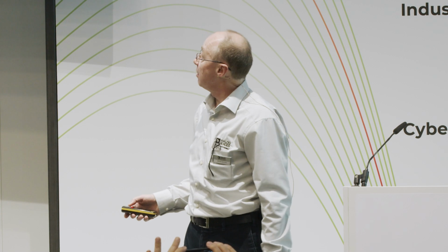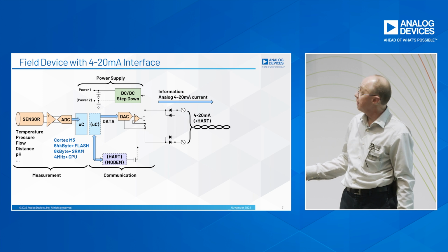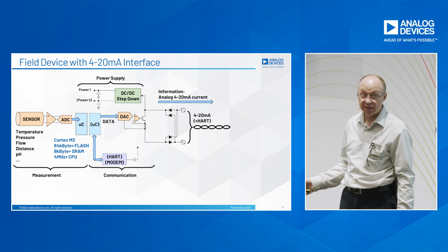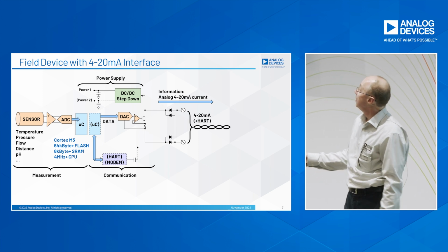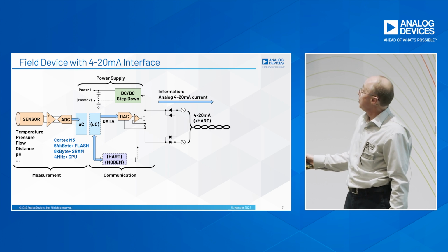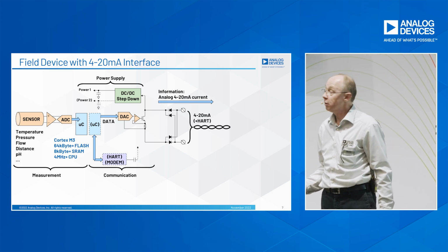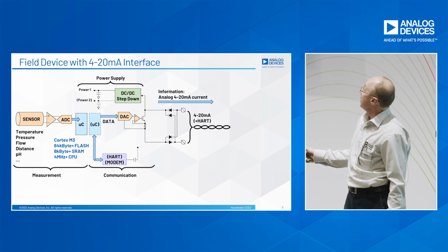Now, architecture of the field instrument itself, and I focus in the presentation on the sensor side. Equal will be applying to any actuators, any valves, and devices like that. So typically a sensor measuring temperature, pressure, flow, distance, whatever needs to be measured there. Some analog front end, microcontroller, maybe two. You can see that it is relatively small on today's scale, small microcontroller, and communication.